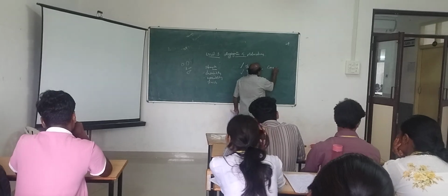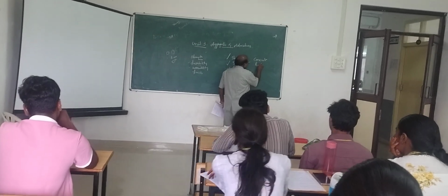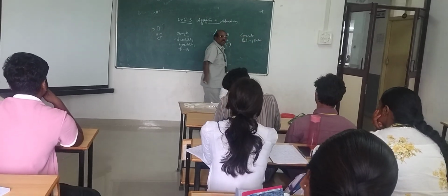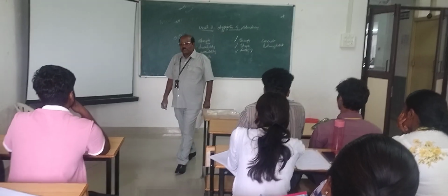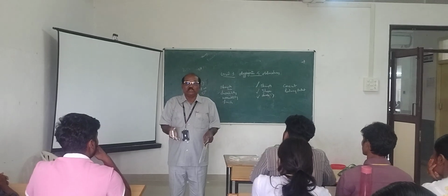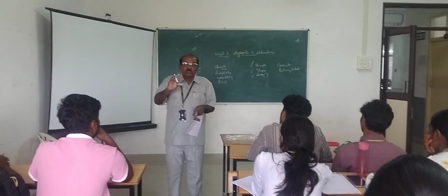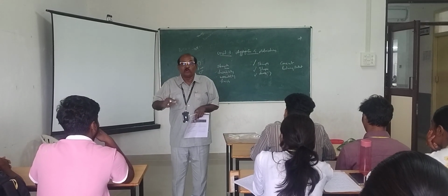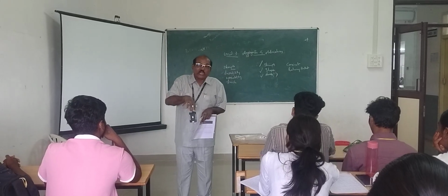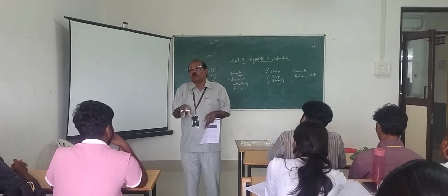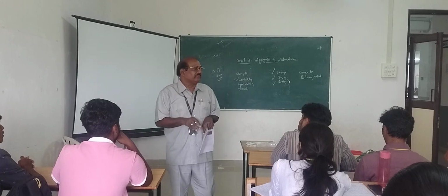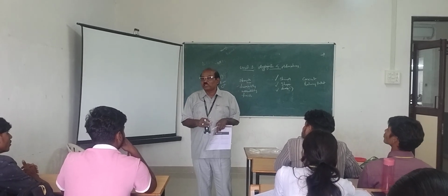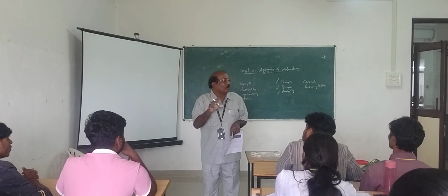That is one. Second, railway ballast. What is the meaning of railway ballast? Did you observe a track which is lying on 40 mm aggregates, not 20 mm or 12 mm, 40 mm or above? So over the 40 mm aggregate, the track is laid down. Why is aggregate required under the track? Because it gives a lot of vibrations and sound while the locomotive moves.